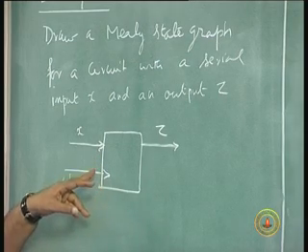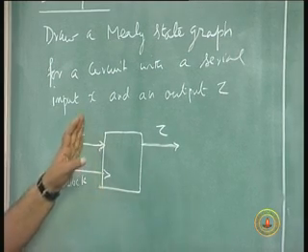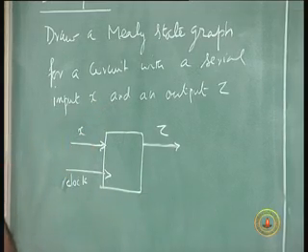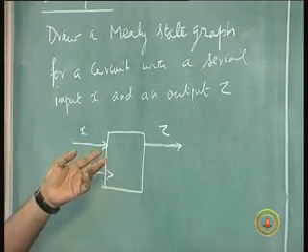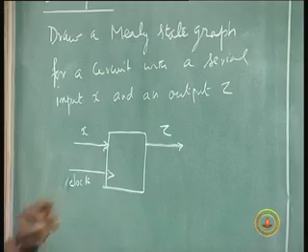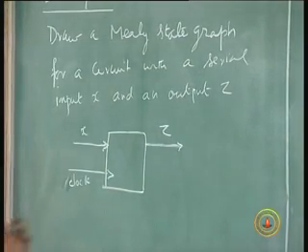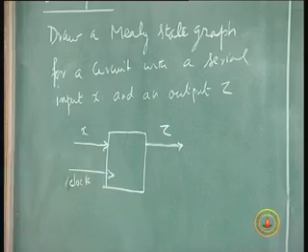The input is sampled at every clock transition. If the value has changed, it will take the new value. If the value is not changed, it will still take the old value. So, it will be a series of ones and zeros. And then we want an output z, also a series of ones and zeros, and the relationship between x and z will be the following.